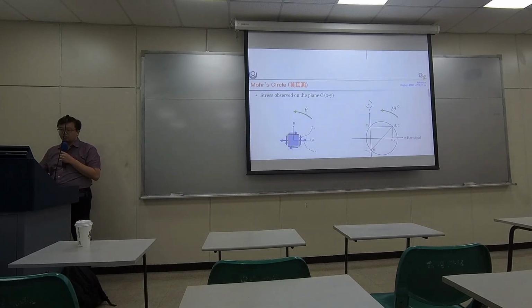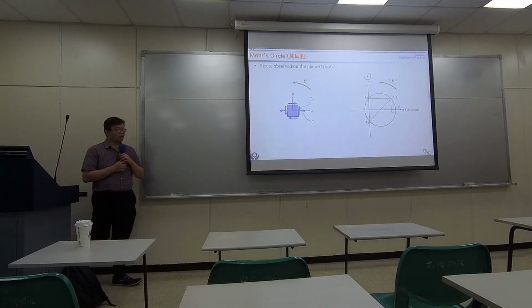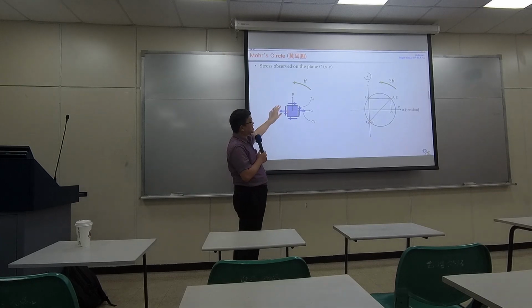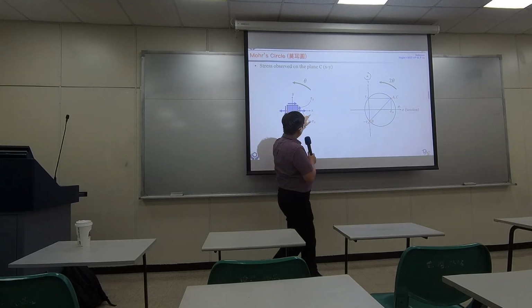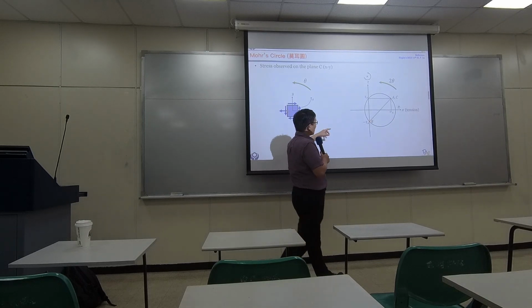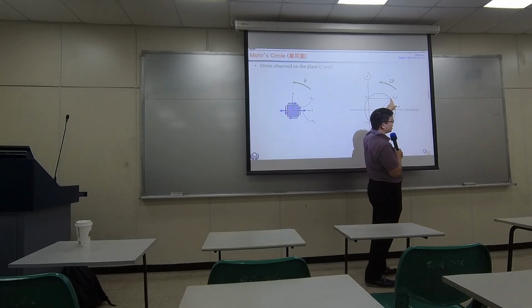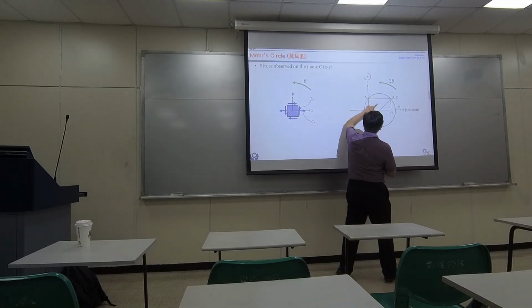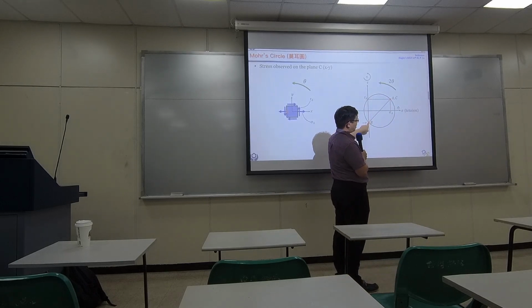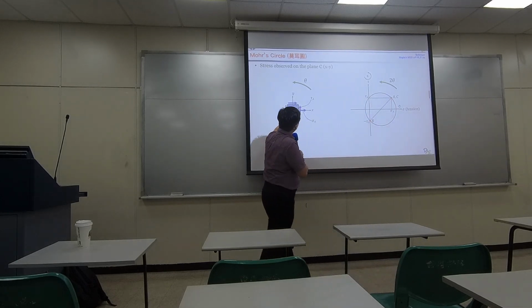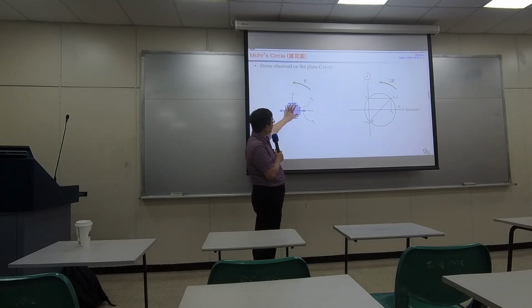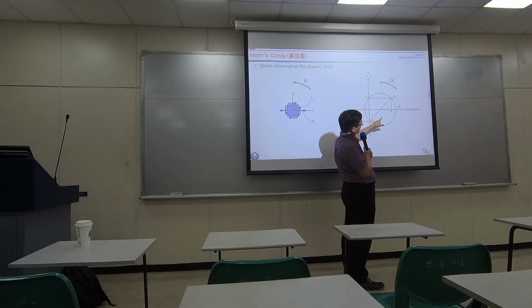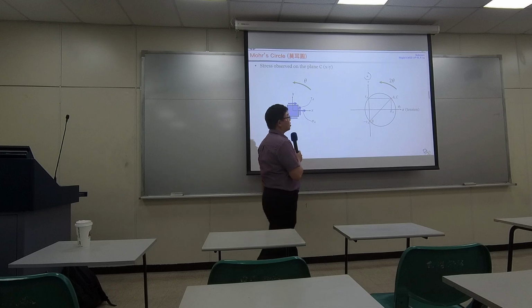If I continue to move forward to point C, I realize the loading condition is exactly the same. It seems exactly the same as A. So it seems like I'm getting back to point A again. And if I keep on moving downward up to here, I will move up to the same point, B here. So if you make 90 degrees of movement in the free body diagram, you are moving 180 degrees in the Mohr circle coordinate.